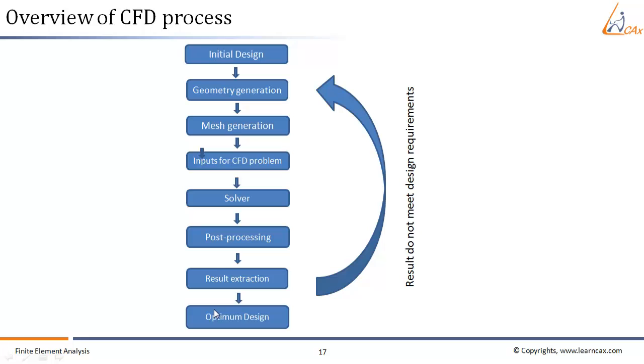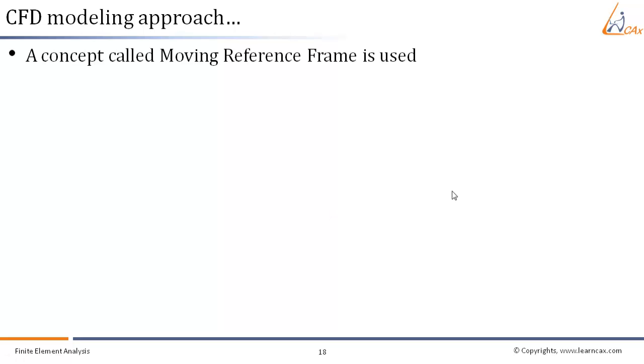like in terms of the head obtained, or in terms of the efficiency, the head versus flow rate curve. All these we see whether they are according to our design requirement or not, whether they satisfy the practical usage of the turbo machinery. If not, we return to change the design and repeat the whole CFD process. So this is how the CFD workflow works in terms of designing turbo machinery using CFD.